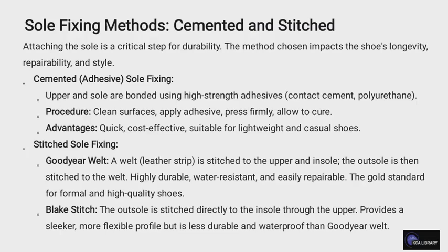We also have stitched sole fixing as another method, and for this we talk about the Goodyear welt. The welt, a leather strip, is stitched to the upper and insole, and the outsole is then stitched to the welt. It's highly durable, water resistant, and also easily repairable. It's the gold standard for formal and high quality shoes.